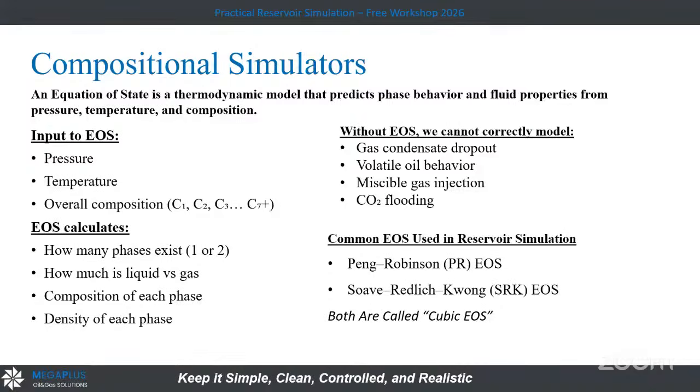It's like the DLE, but here the gas. We will open, so we got the oil and gas and analyze in each pressure step, we will analyze this composition. So by CVD, we can have this table at each pressure. As you see, we have the composition in mole percent. It must be 100% from C1 to C7 plus, but it could be until C25 or C30.